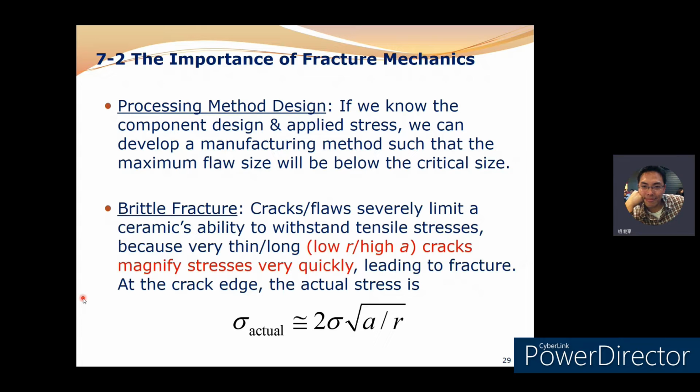If our material is brittle, such as ceramics, alumina, or glass, and there's a crack inside or on its surface, if the crack size is long and the crack radius is small, that means highly concentrated stress will be located at the crack tip.